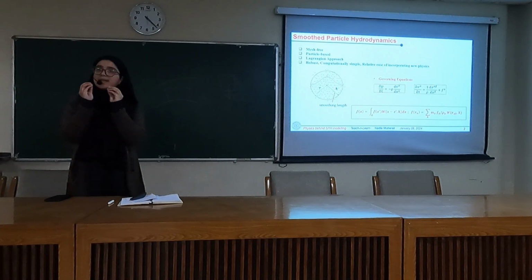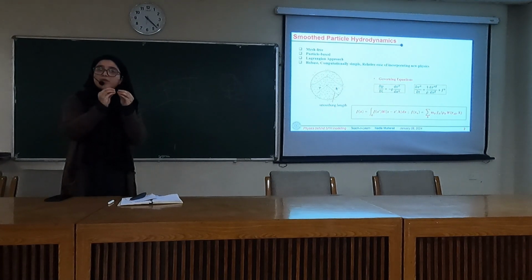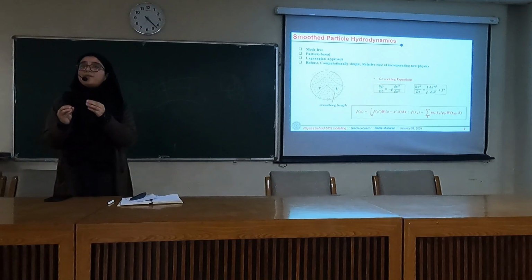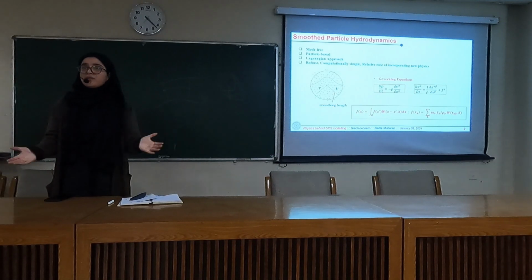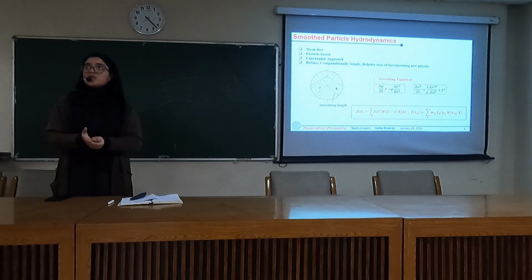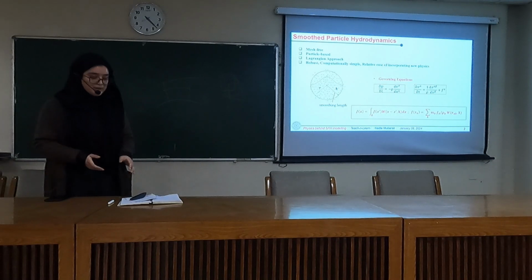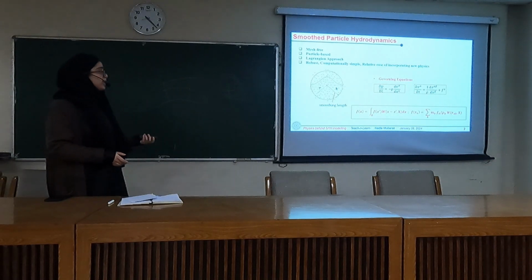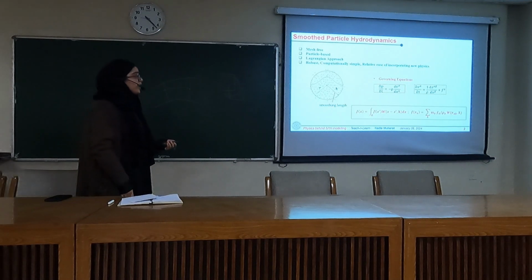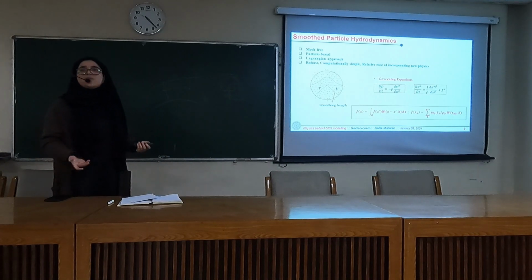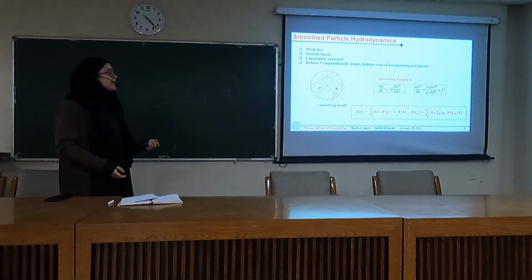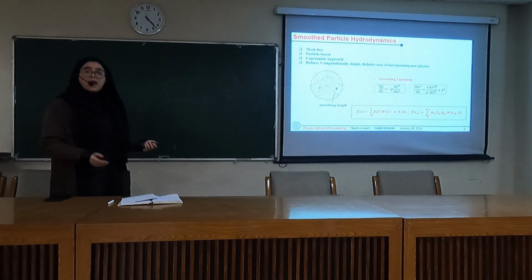And when we calculate these properties for different particles, we need to know the overall behavior of the fluid from that. So it needs interpolation. That interpolation is taken care of by the kernel approximation, wherein f of x is any field function, let's say velocity at position x, and w is the weighting function.